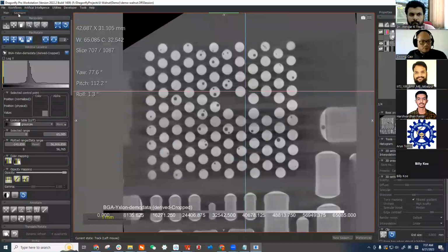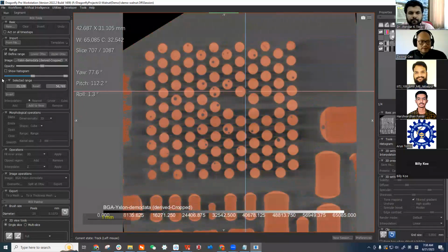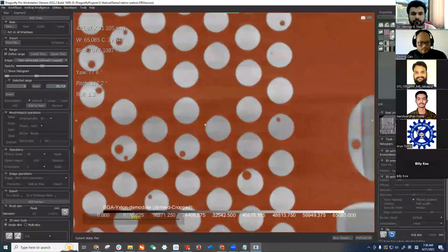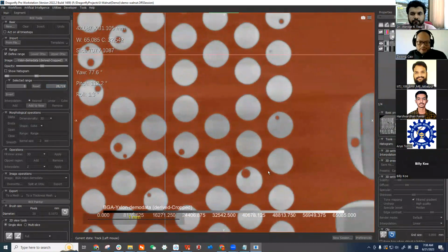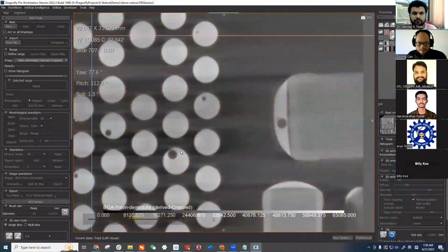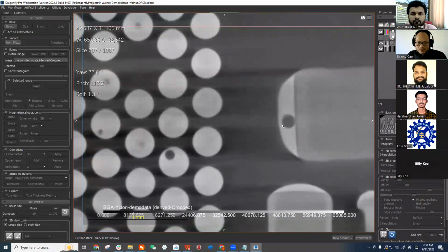Starting with this image, if we do the very traditional way, which is the intensity threshold, we will probably find the pores have lower intensity than the balls, but it's difficult to differentiate these pores from the background, especially from the other pores, like in this component, which has exactly the same intensity. But this is not the target that we want to segment or label.